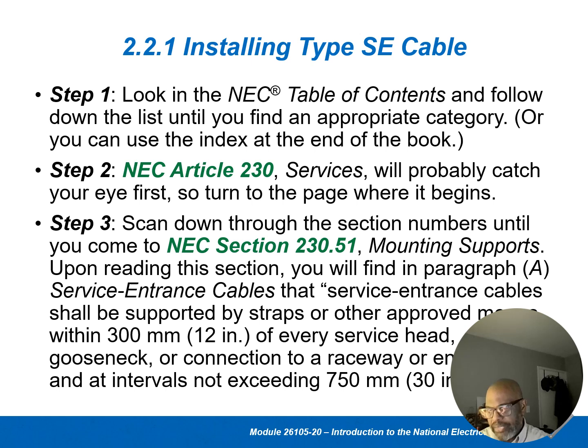So in other words, if you're going to strap it, they want to make sure that the service cable and the conduit on that wall are secured in a way that it's not going to be loose or flapping around or moving around. So it's going to be a solid installation of that main power source coming in. It's a service entrance. That's the main power coming into a building.